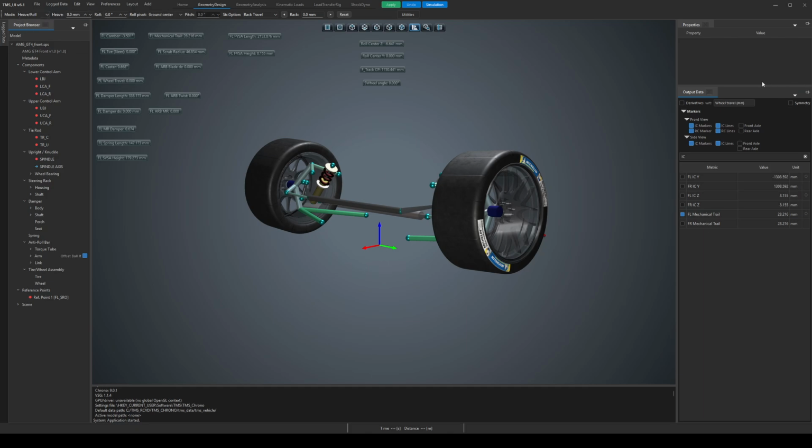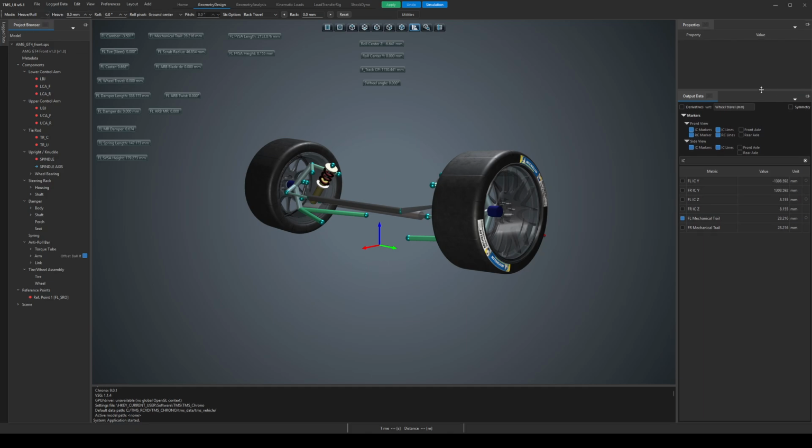On the side of the screen sits an output data panel, used to choose which metrics appear in the main graphics window. Enabling a metric brings up a simple dialog asking for the label's initial position, expressed as a percentage of the window's width and height. After the initial placement, holding Shift and left dragging moves the label anywhere on the screen. The application remembers each position, so the layout persists across sessions.